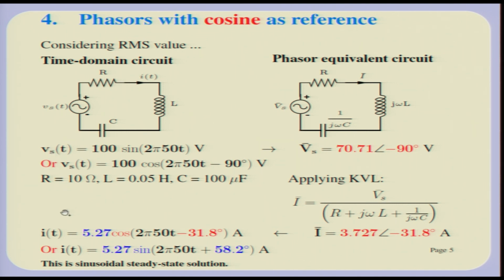Okay. So, that is very interesting. So, you can actually stay in the phasor domain; you need not come back to the instantaneous values, you can do most of your computational work simply in the phasors, with the implicit understanding, of course, that the phasors represent sinusoidal quantities in the time domain.